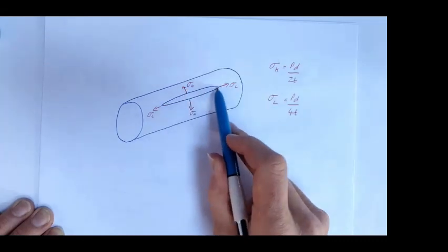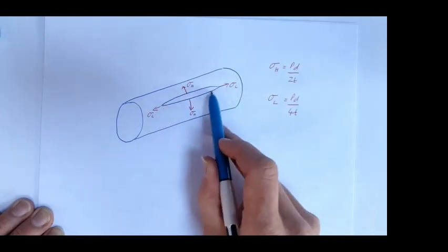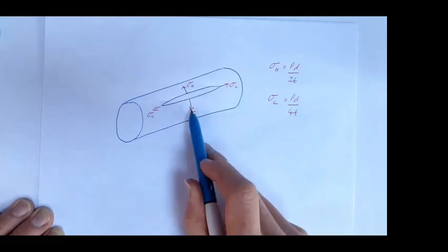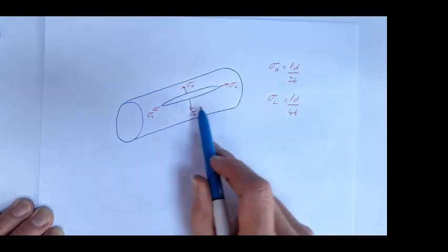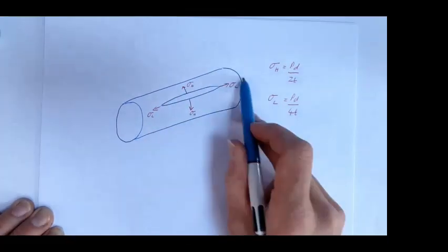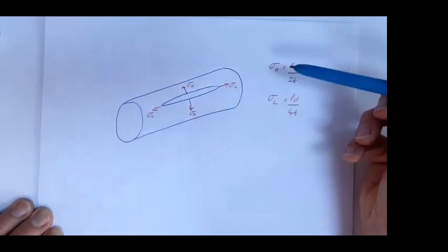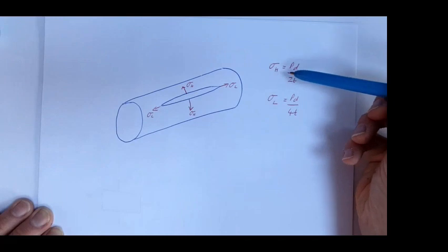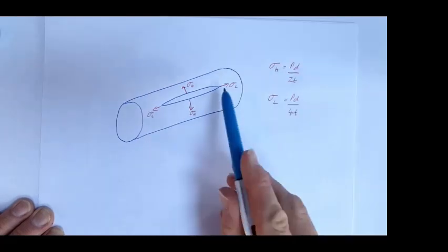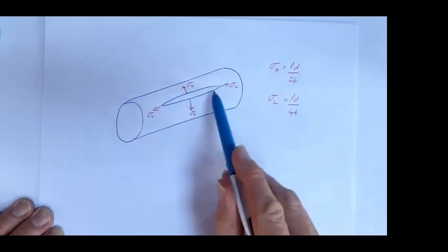So we get our split in our sausage running like that because our stresses are twice as big in that orientation. So that's quite a nice visual application that everybody is aware of, which clearly shows that our hoop stresses are bigger than our longitudinal stresses because of the orientation of this failure.